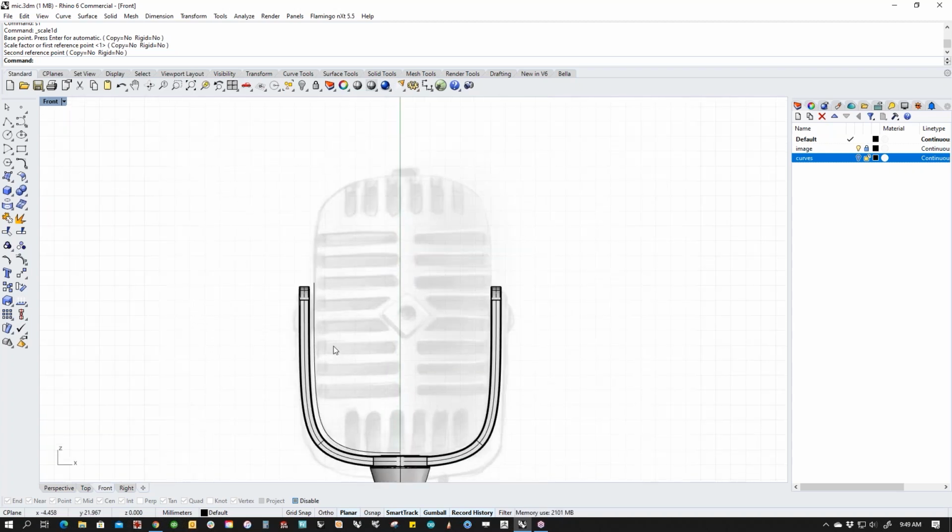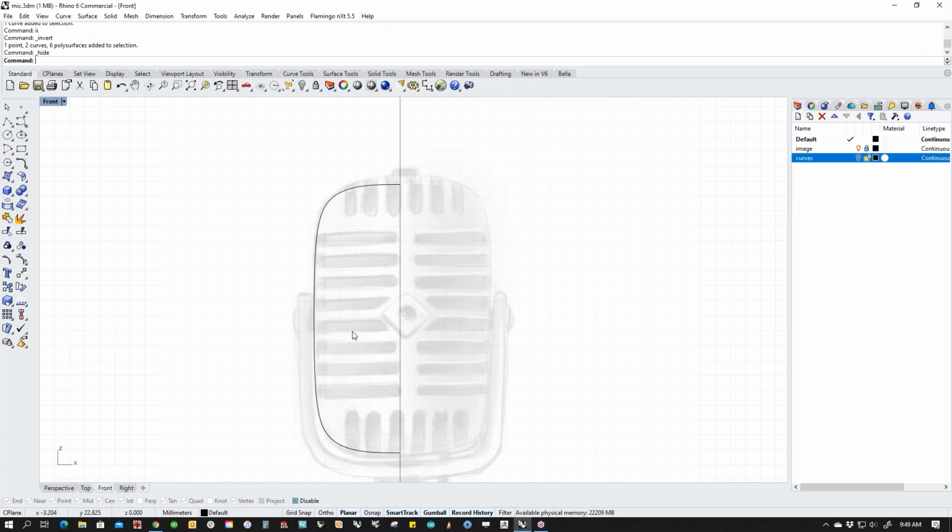And I may actually mirror this around where the pivot is. So let's decide where the pivot is. Let's draw a line through there and we'll save it for later. But I'm going to trim this. And then let's mirror this curve. And then let's do a little looking, right? We want to make sure, so that we have centerline tangency, which points are lined up.